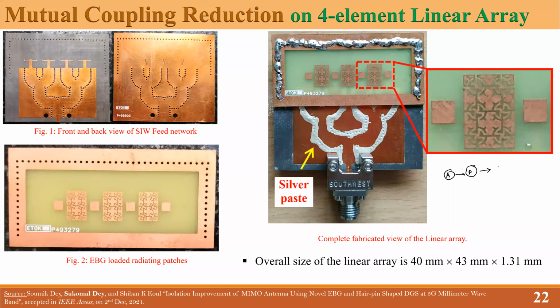That higher element model, one can make in a linear array configuration, or in an orthogonal array configuration. We have made a linear array configuration. You can see the different parts of this, and finally see how complicated it is. We keep all these things bonded with some soldering wire, and finally we got this antenna. It gives very good performance. It works in the 5G band, and gives a good standard gain of 13.3 dB.